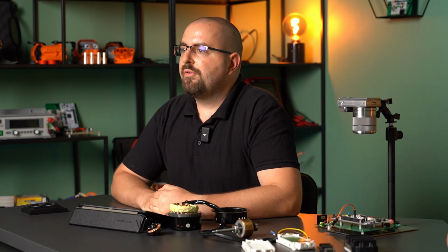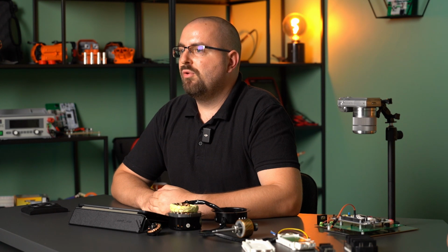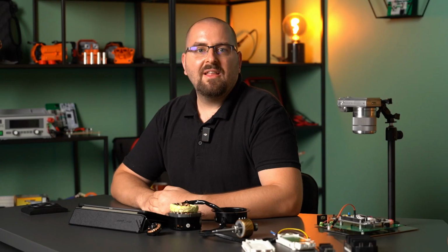They get their name from the fact that the speed of the rotor is synchronous with the rotating magnetic field. The stator of these machines, like that of asynchronous machines, is a coil which, when supplied with alternating current, generates a rotating magnetic field. Part of the motor may be a permanent magnet or a DC excited electromagnet, or possibly a non-magnetized ferromagnetic material known as reluctance motor, but this type is not discussed in detail now. The rotating magnetic field interacts with the magnetic field of the rotor and rotates it.